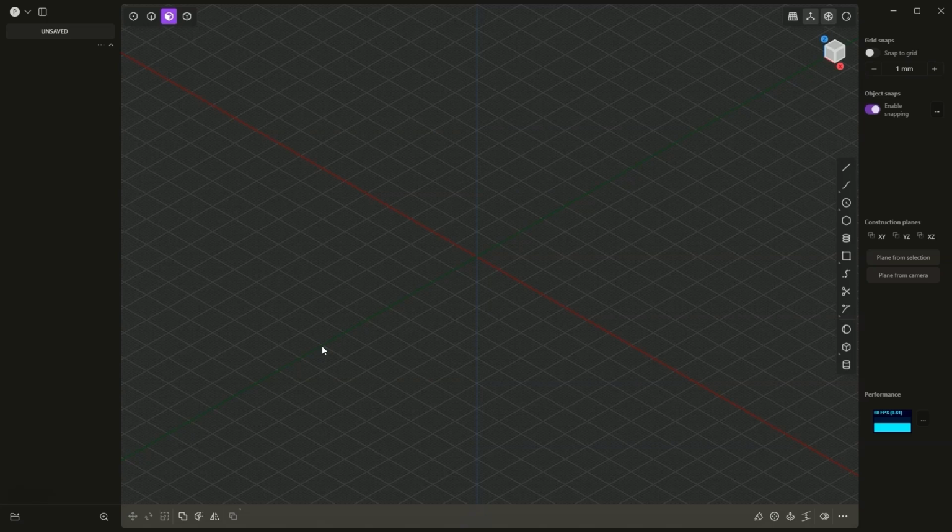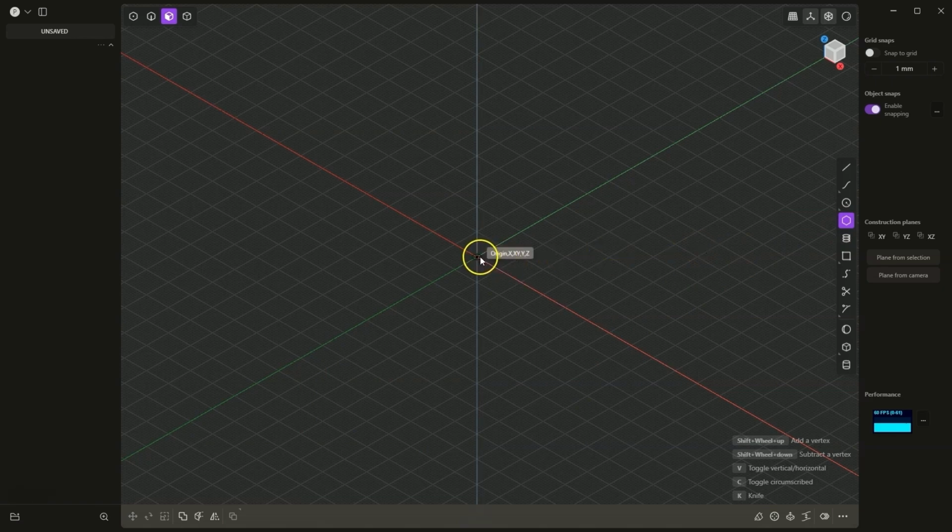The next interesting operation of creating 3D solids is extruding a profile along a path. Now we will create a sketch of the profile. We will create a polygon here. Select Drawing Polygons, and at the beginning we determine the center of the polygon. Place the center of the polygon at the origin of the coordinate system. By default a pentagon is created, but by holding the Shift key and rotating the mouse wheel, we can add or subtract the number of sides.